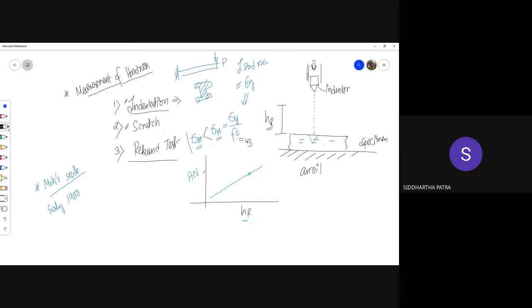Okay, so the point I'm trying to make here is yield stress, which marks the initiation of plastic strain. If I have that value from an experiment, let's say a tensile test, then I can use that value directly in a designing operation. In a designing job, I can directly use that value. Such is not the case with Izod number.